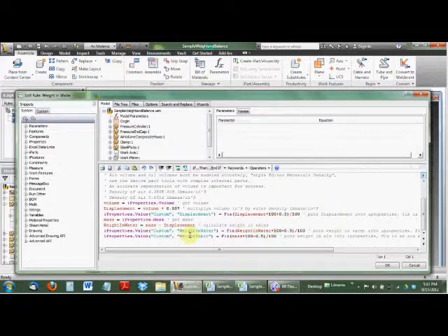And basically what happens is you create a variable. In this case, in this lower line, it's mass. We got mass right from Inventor. We just said mass equals iProperties mass, and we added this fixed thing. This fixed thing actually formats the output of the iProperties. We're basically keeping it to 2 decimal places here, and that makes it easy to display later on in your drawing and or in a spreadsheet.